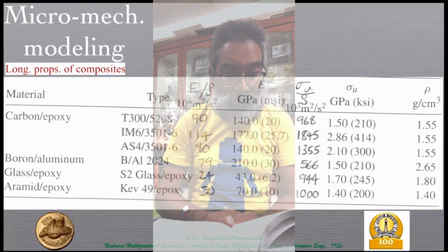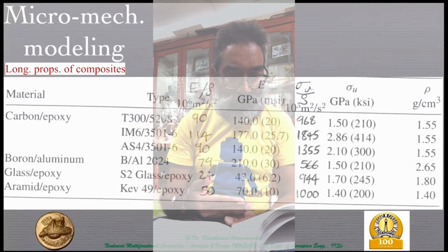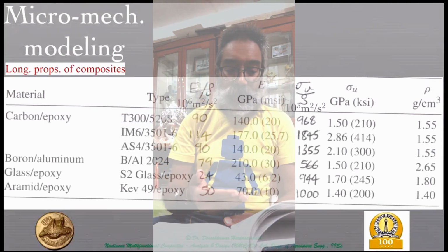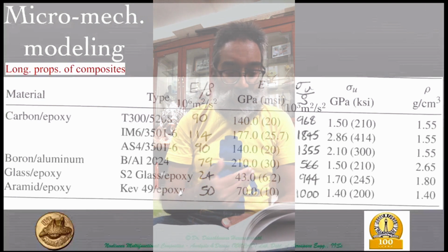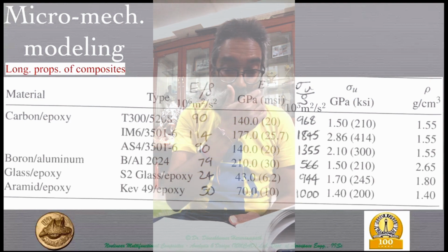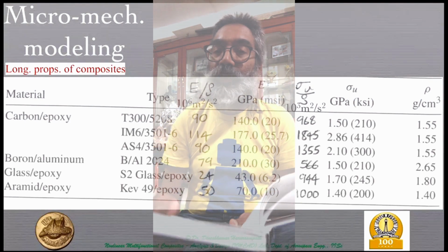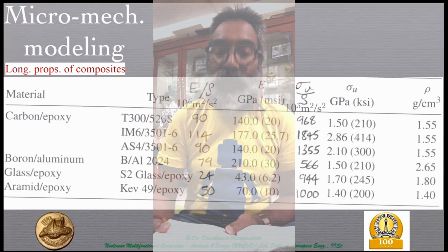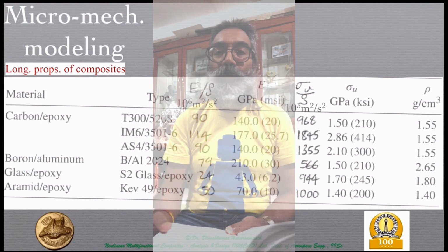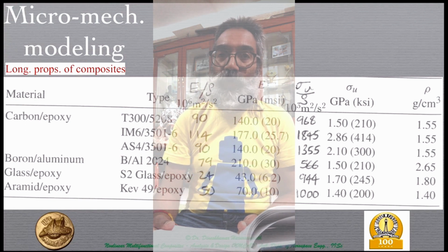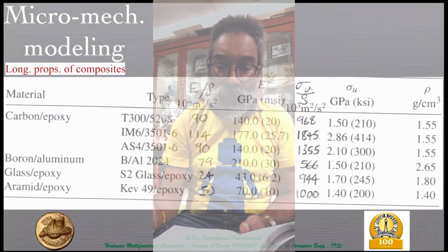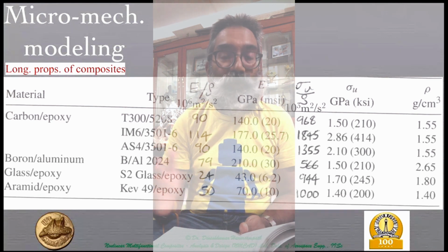So it's only in terms of the ultimate tensile strength you see a difference between the 2024 and 7075. In the case of aluminium 2024, it is 449, whereas in the case of 7075, it is 538. So as your textbook says, there are two different heat treatments which are typically used with 2024, T3 and T42, in terms of how the metallic alloy is actually processed. And irrespective of those two heat treatments, in both cases, the 2024 has excellent fracture toughness and slow crack growth rate, as well as good fatigue life.